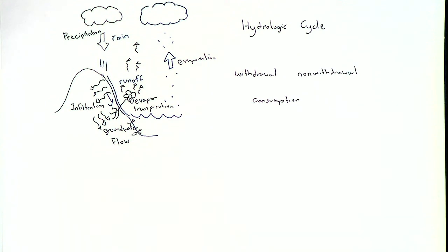You are designing a water supply system for Marietta. Are you going to design for 60,000 people? Why not? It grows every day. It can grow, okay. Let's suppose they have a cap on how many people can live there, and only 60,000 can live. Are you still going to design for 60,000 people? No. Why not? Because not everyone is using the water at the same time. Correct. Also, people travel in and out, and they don't live here.